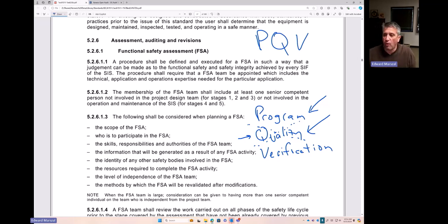Okay, that's a pretty good quality, that's pretty definitive, but you might have a program that says the PLC logic vendor shall determine what's appropriate. I don't know if that's as good of a quality of a program as definitively saying we are always going to use manual resets unless otherwise specified with justification.